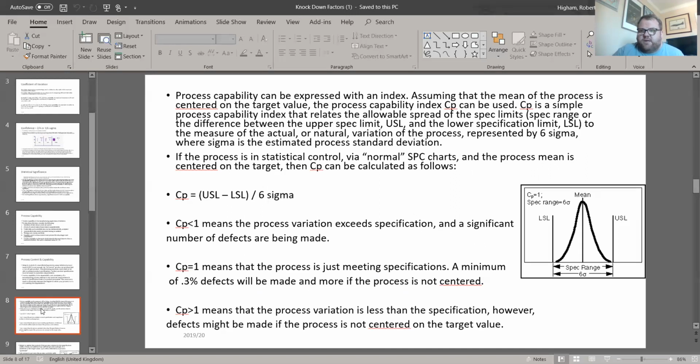So that's the minimum expectation of that material in particular, is what we normally look at. So when we have this lower spec limit, these are the values that we already have. The reason they give that as a limit is because they have a 6 sigma level confidence that all of the data will be beyond that. So the actual true mean of our test data will always be higher than that lower spec limit.